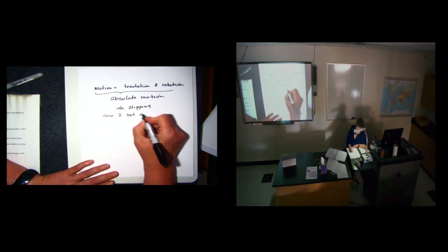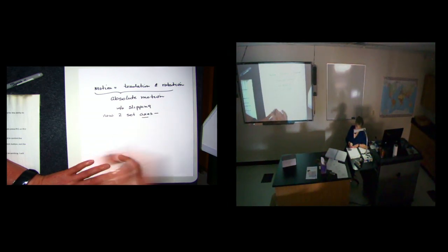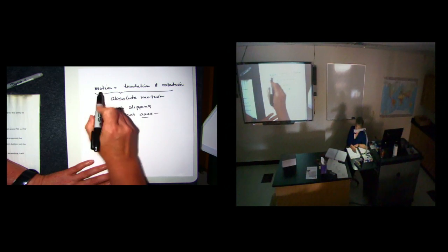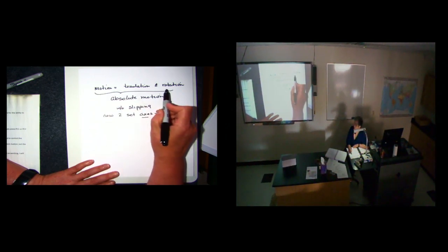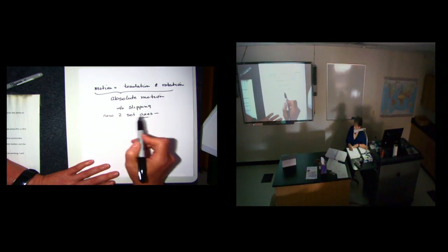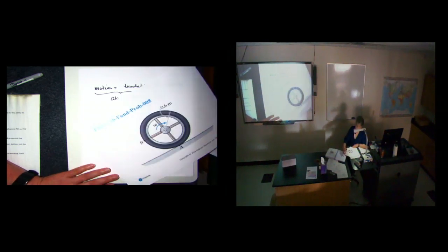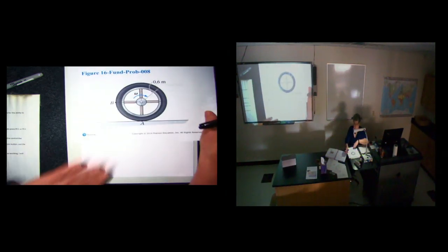So it's very similar, but what we can do now is that the velocity of B is going to equal the velocity of my center of gravity, my translational motion, plus my rotational motion, where I'm using a relative definition of the position that I have from A to B.